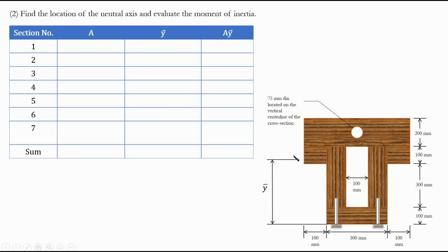Okay, and remember what the equation is for the flexural formula. It's My over I. So now for M, which is moment, we have M. What is y and what is I, the moment of inertia? We don't know those. So y has a component of neutral axis in it. I also includes some components of neutral axis, and of course the capacity of the member to resist flexural deformation, which again has to do with the moment of inertia, the second moment of area of this cross section.